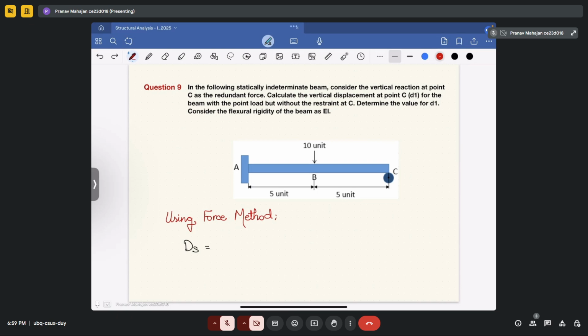Let me write here with the red pen. So for a hinge, the number of unknown reactions is 3. In case of this roller, or you can say prop support, the number of unknown reactions is 1. So your total unknown values will be 3 plus 1 minus the number of available equilibrium equations, and if you calculate the total degree of indeterminacy, it will come out as 1.